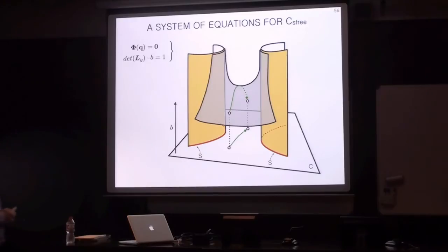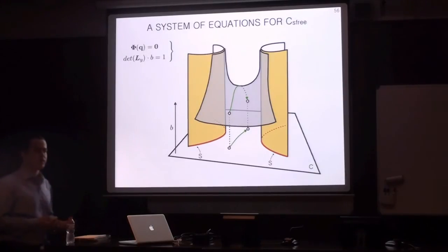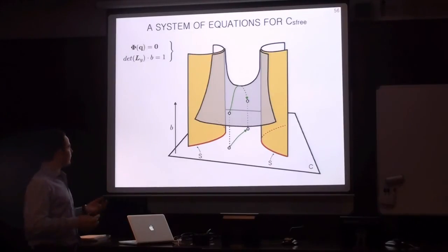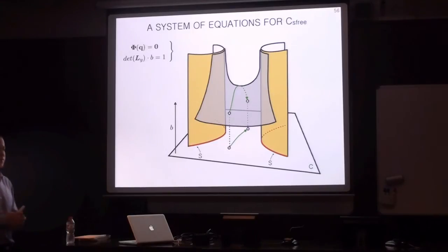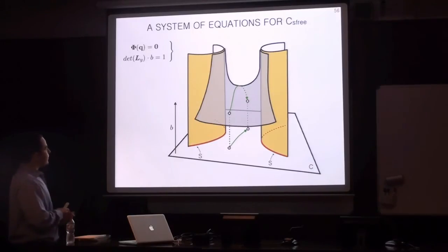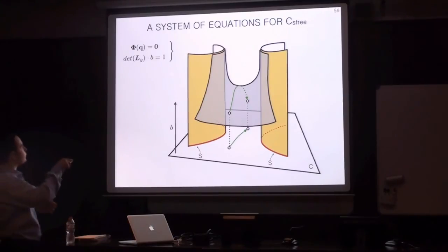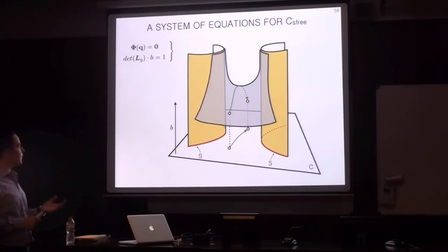We can also see that the Jacobian of this system of equations is never rank deficient. So this extended manifold is in fact a smooth manifold. And this is very convenient to apply a continuation technique because we don't have to worry about the presence of non-smoothnesses like bifurcations, for example. And note that if we want to define a clearance with respect to the singularities, the only thing that we need to do is to set a maximum allowed value for the variable b. So now that we have these systems of equations that characterize the singularity-free configuration space, we will see the higher dimensional continuation technique that allows us to explore the solution of this system of equations.